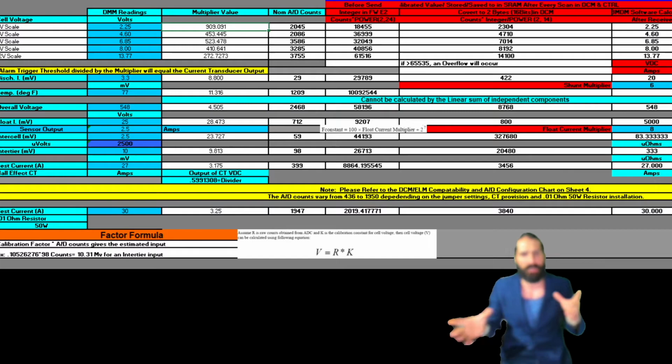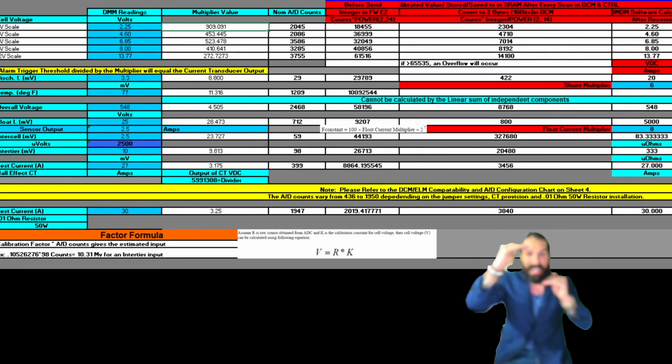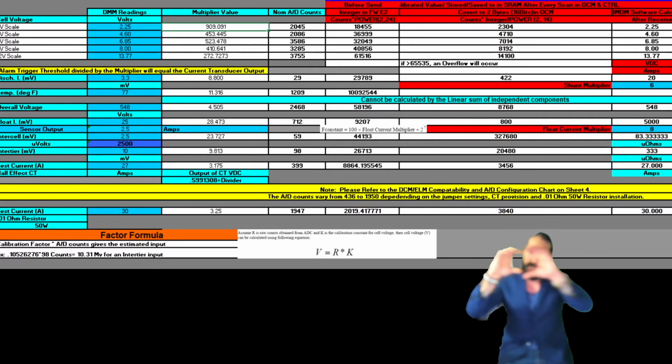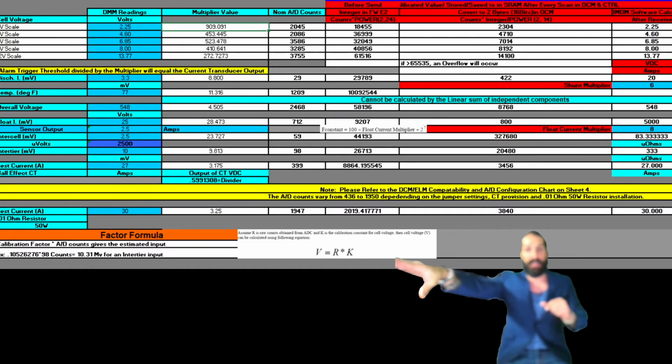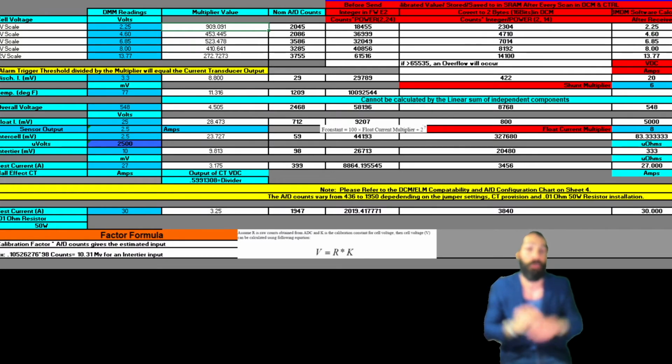I know it seems a little difficult to comprehend if you have never worked on some of these systems, because all you see is a bunch of numbers and values. But just understand that the divider circuitry is taking an input and scaling it down so we can fit it through a window. And that window needs to have enough buffer on the top and a buffer underneath so it can move appropriately within that input variable so it doesn't hit a ceiling. Essentially it's like first in, first out with a water glass, like a memory overflow. You won't be able to see the high end if the voltage goes over 13.4. You would never see it because you miscalibrated it incorrectly.